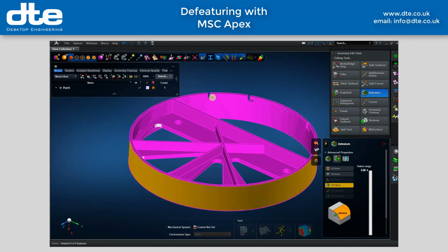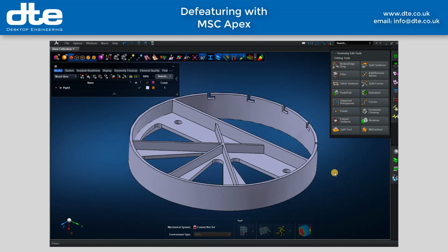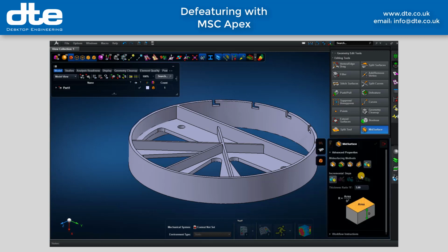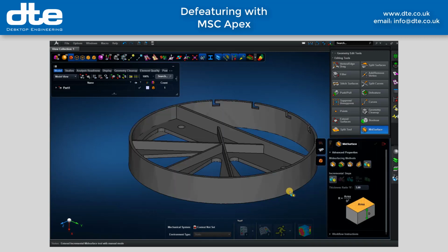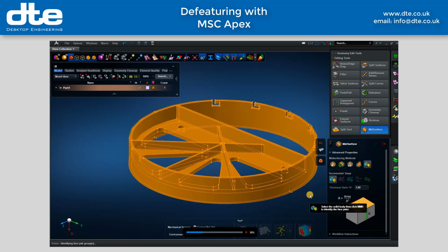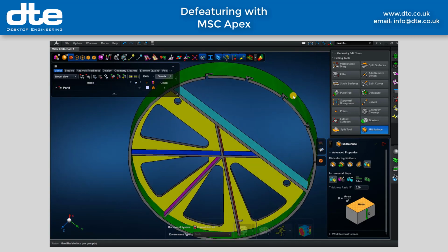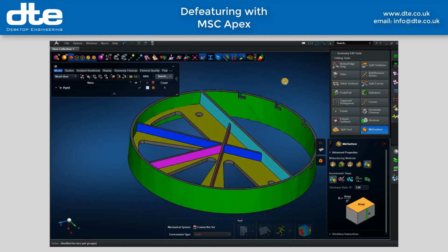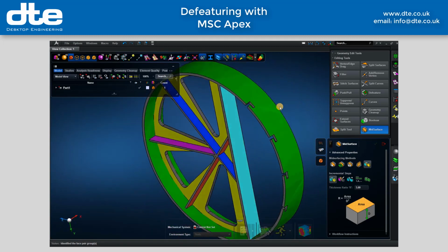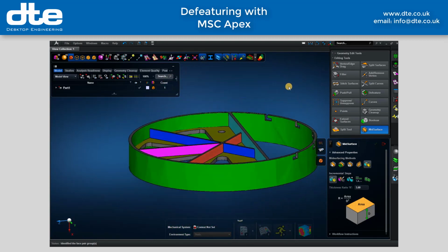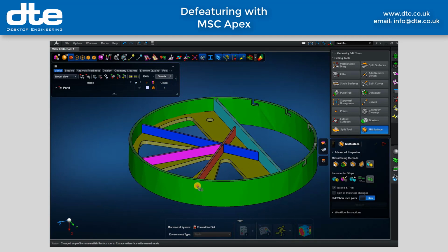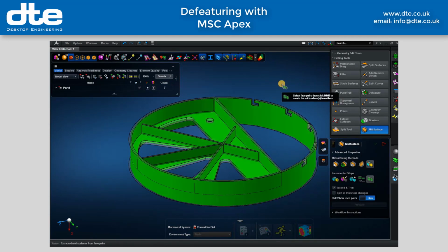and the last things I want to remove are these regular notches. Apex doesn't have a tool for taking those out automatically from the solid body, but it can from a mid-surface. So I go into the mid-surface tool here and I pick the part, middle mouse button. Now Apex goes through the model and looks for opposing surface faces and pairs them up and color codes them so that I can look through the model and see whether it's picked up the appropriate matching faces, which it appears to have done. I can then go to extract those as a mid-surface.